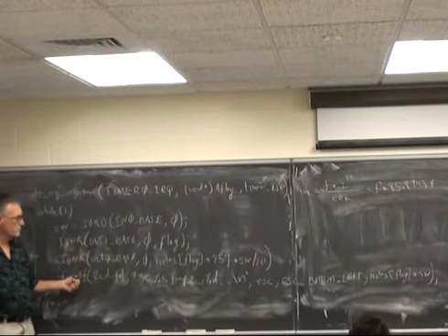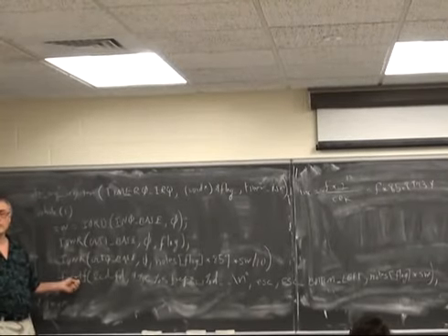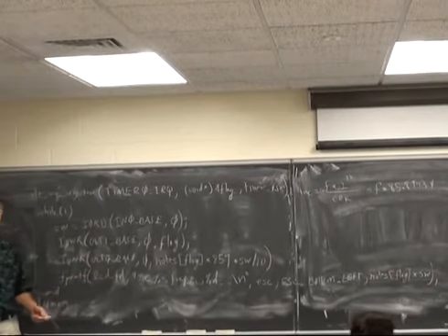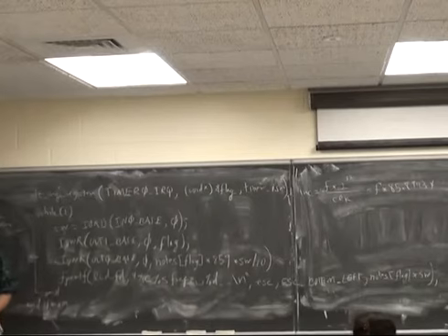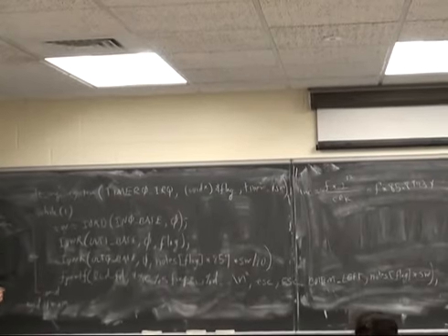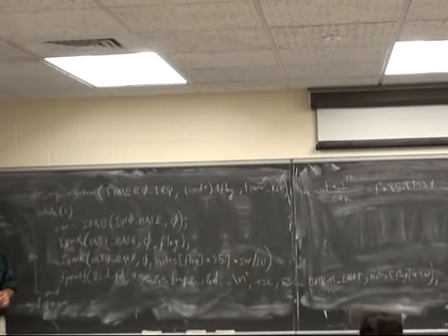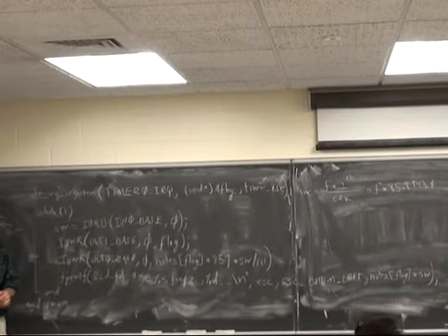But this kind of structure makes it very easy to do an fprintf to the LCD for debugging. So you can always find out where in your program you are. You can put little messages up. The LCD is 2 lines of 16 characters. It's not huge, but that's quite a lot of space for debugging. It is not, however, very fast.